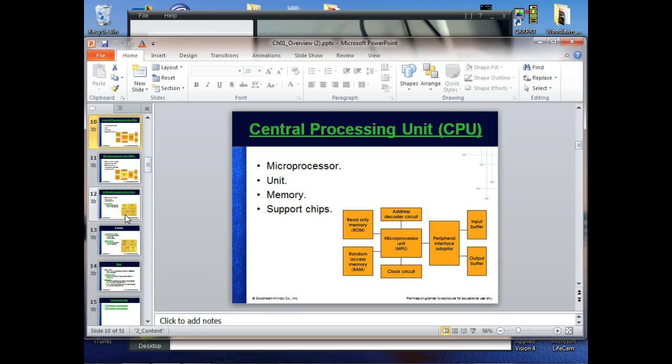So we have trade terminology and then we have actual terminology, right? It's just like we call a board a 2x4, but if you measure it, it's not going to be 2x4. It was set up so it would give you 2 inches when you put 1/2 inch sheetrock on the outside, so then it would measure 4 inches. That way you'd know how far out you would have to come. Everybody calls them 2x4s, but they're not. That's what we call trade terminology versus actual terminology.